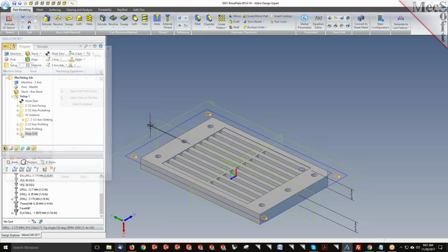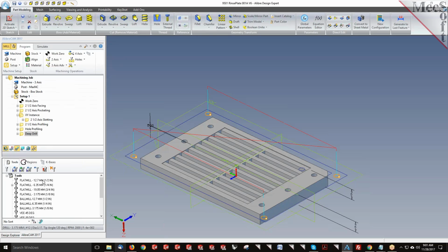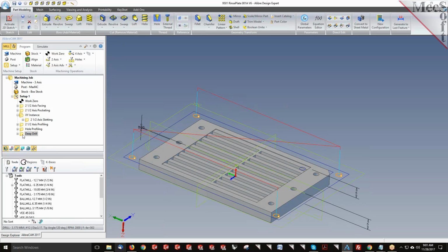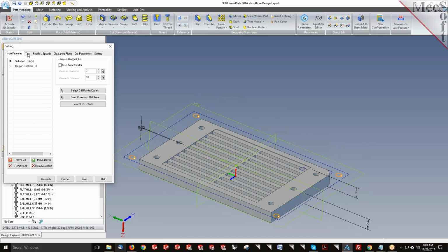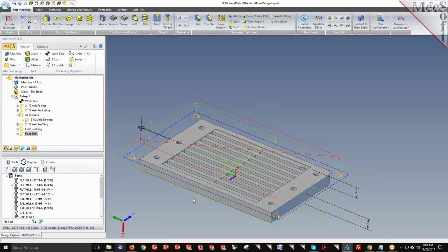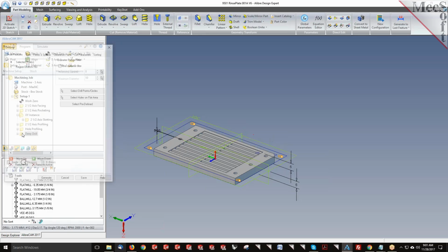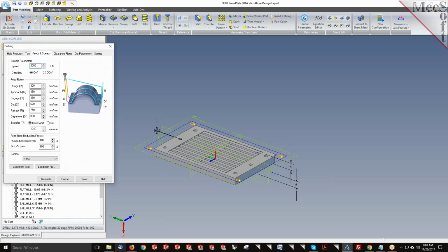Maybe this is a little trivial, but on that pecking operation, if you want to change the feed rate for the peck, where is that information? On a peck drilling operation we output a canned cycle for drilling. Typically it outputs a G83, and then a cycle feed rate. That feed rate is over here.